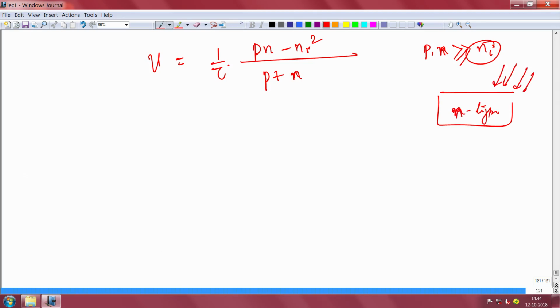Because it is n type, the excess electrons that you generate, suppose delta n, because you are shining light, will always be equal to the excess holes that you are generating. But because it is n type doped, this quantity is much smaller than the background n type doping, so it can be neglected in comparison to n type.